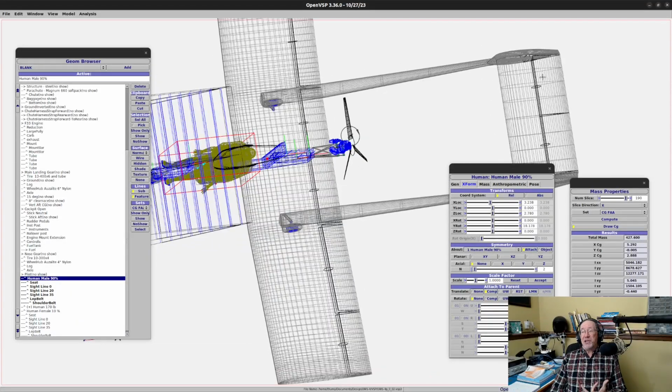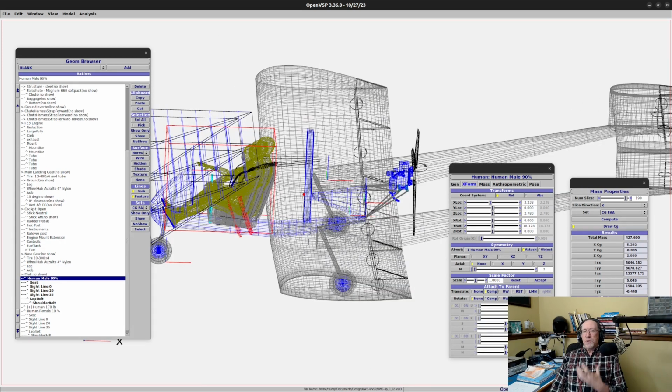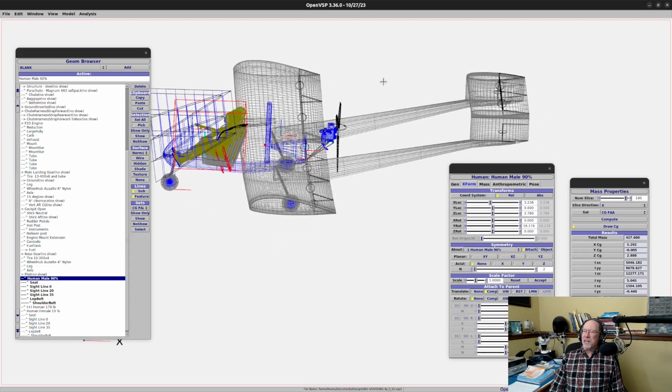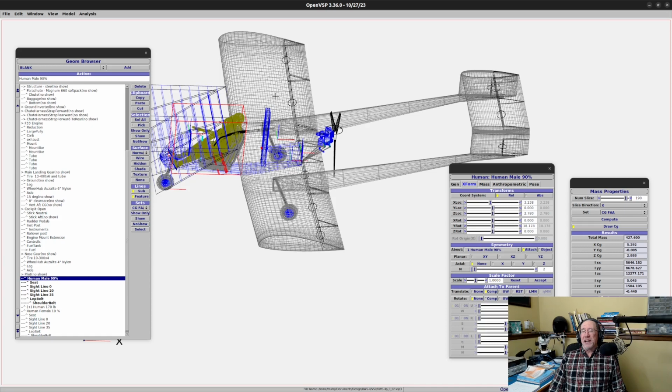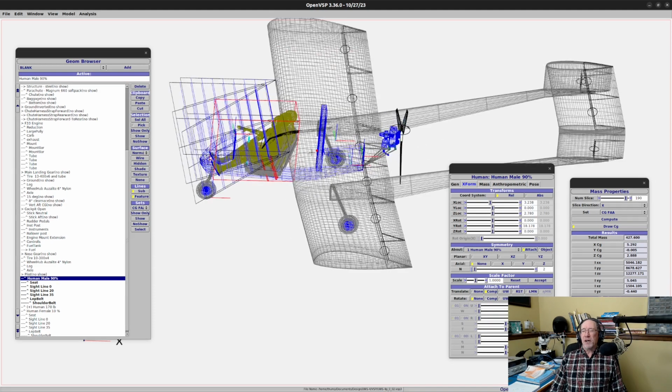So if I change the size of the horizontal tail, it's going to be the chord that will change. So once we get through the static stability calculation and we get the final size for the horizontal tail, and I'll probably at that time also have a final size for the vertical tails, then I can start detailed design on the wings, the booms, and the tail. And I don't think any of those dimensions from that point forward will probably change. So that portion of the airplane, where those weights are, will be fixed. So they won't change the CG anymore.